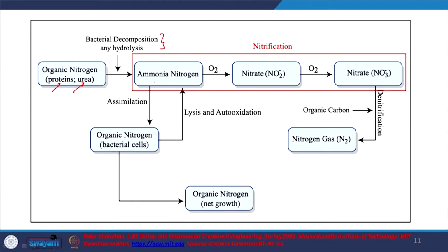And some of this ammonia nitrogen will be used by the bacteria. I think we saw that it was around 12% of the nitrogen content. This we looked at when we were looking at the oxygen requirements, right. And we saw that, or we deducted this amount, let us say. And again there is going to be a cycle, because you are going to have lysis, or death of the relevant microbes and such. So, more or less you have ammonia nitrogen that is in equilibrium with the organic nitrogen, but the one within the cells itself. So, depending on the kind of bacteria and the concentration of bacteria, you are going to have a balance between ammonia nitrogen available for oxidation and the nitrogen in the bacterial cells.